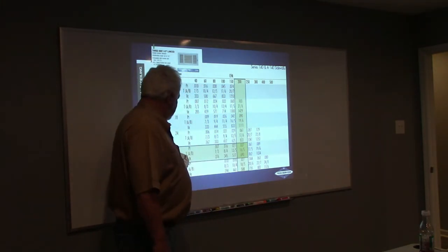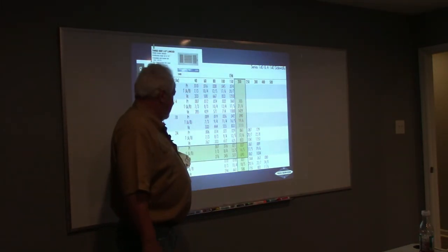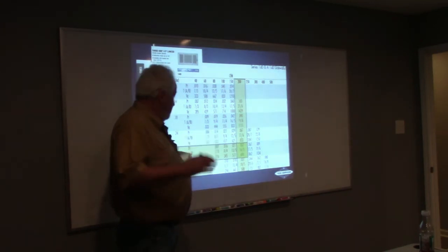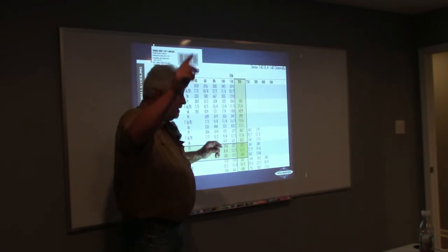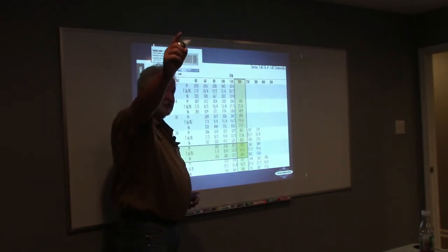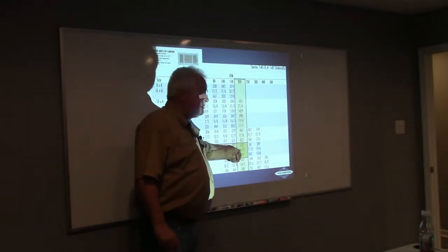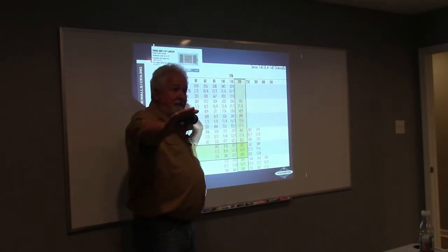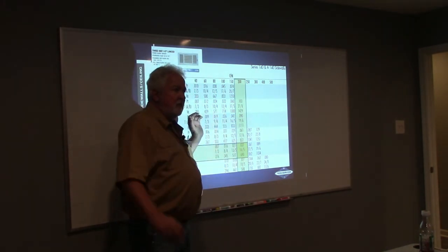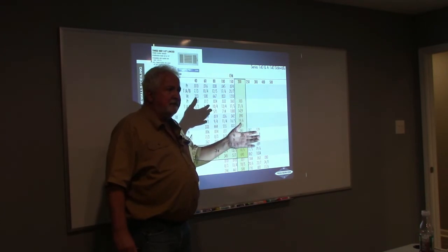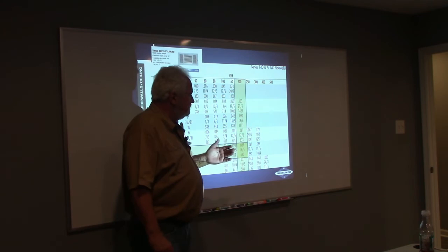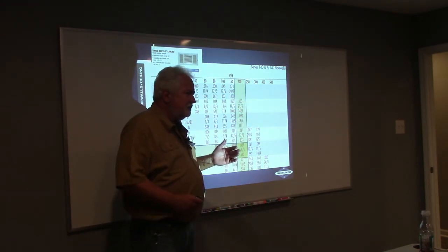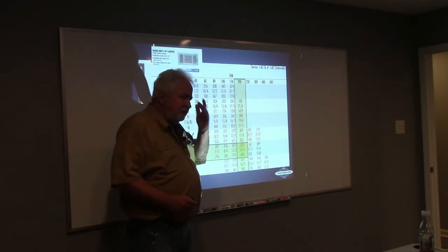It says the throw through A and B. A is going to be the big section, and B is going to be those smaller sections right there. So the throw is going to go 16 feet this way and 5 feet this way. We had a 20-foot room, and we wanted to keep that somewhere between 13 to 15, 13, 17.